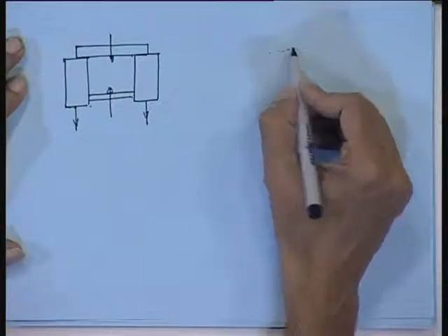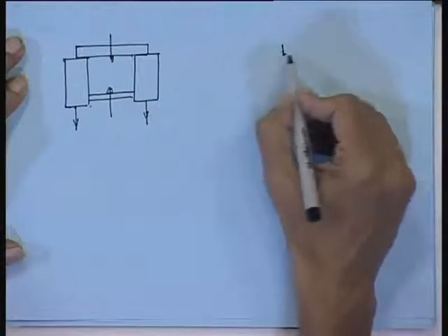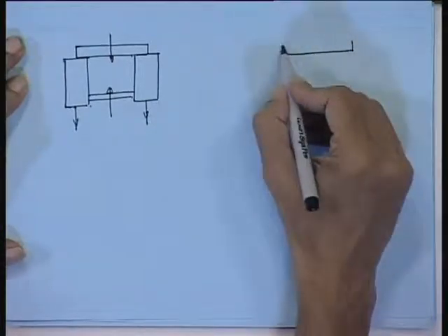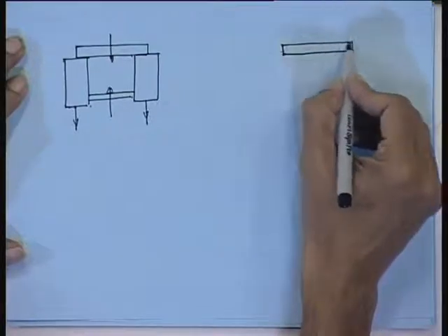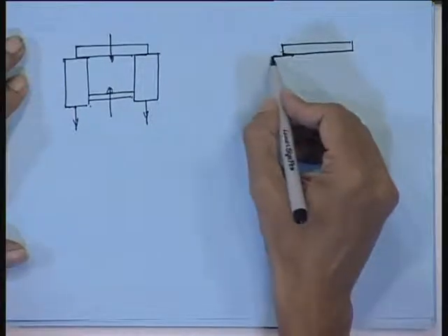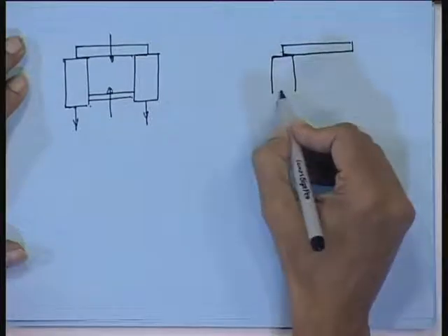Now, the TLP is displaced. So, there is an offset. Now, as a result of this offset, what has happened? There is a set down. So, you calculate vessel set down. So, this is your new configuration.